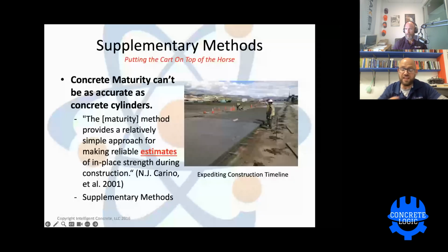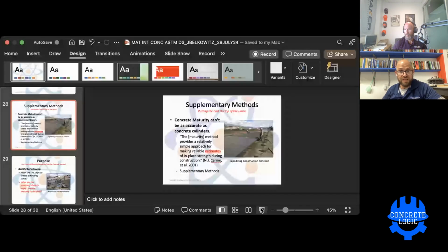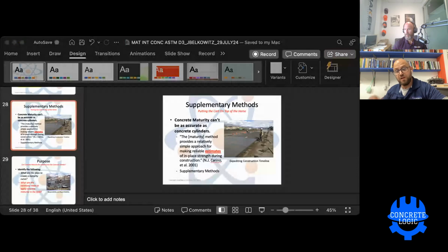And this is Nick Carino. Again, if you haven't met Nick Carino, I haven't met Nicholas Carino, and I want to. He's quoted: the maturity method provides a relatively simple approach for making reliable estimates of in-place strength during construction. That easiness, that customer experience, is based on doing the preparation work, and yet it costs money. There's a lot of work involved, but either that or you're going to pull forms too quickly, or maybe you're waiting too long to pull. Maybe you could have pulled forms 8 hours earlier.